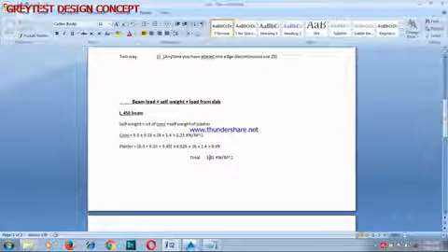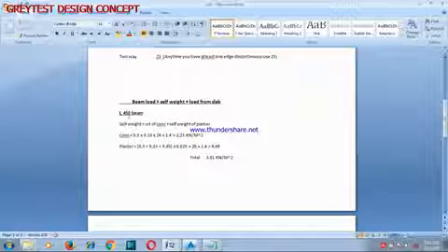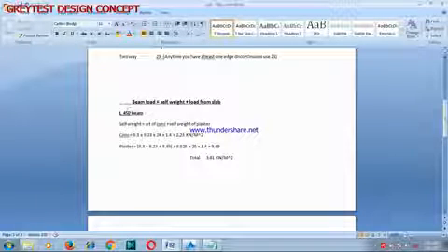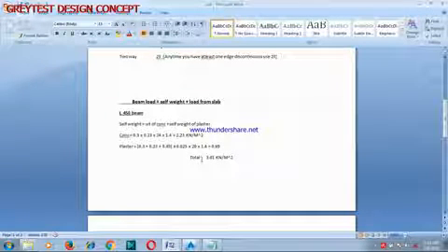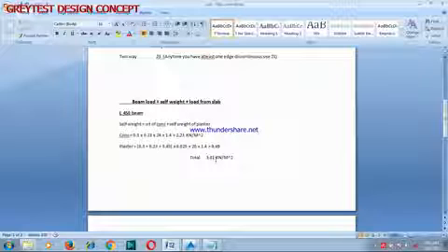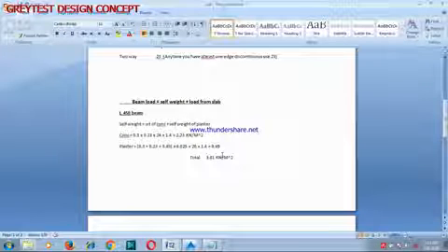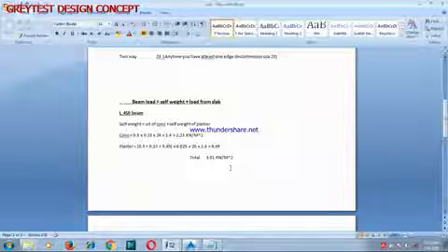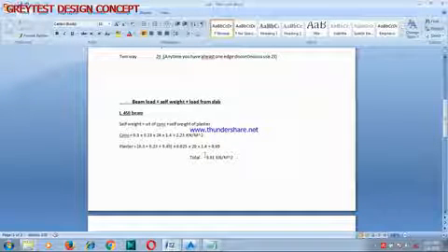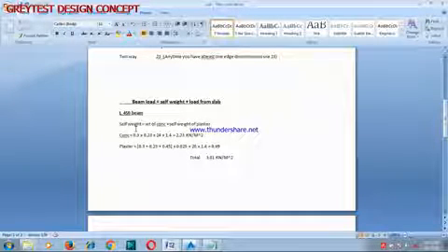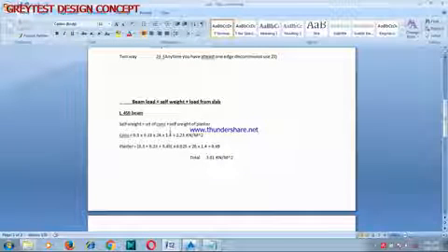Now when this depth of beam changes to maybe something like 600, mind you, this value is not going to be 3.01 when you are designing for a beam of maybe 230 by 600. Okay, it's going to change from the values we provided here.